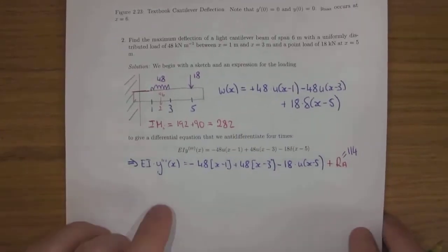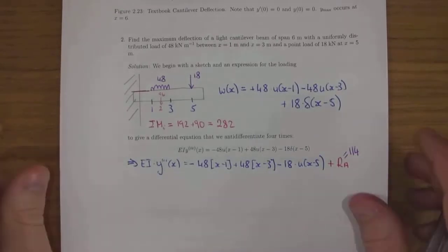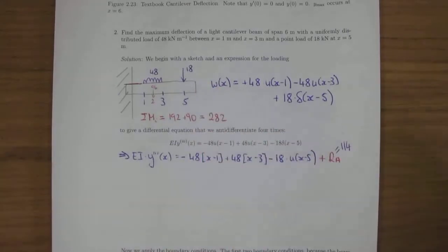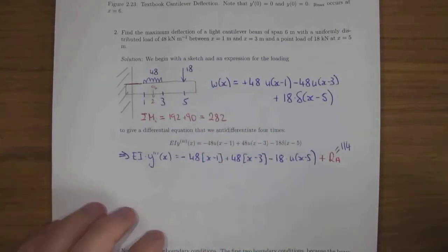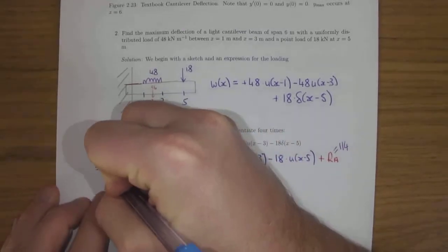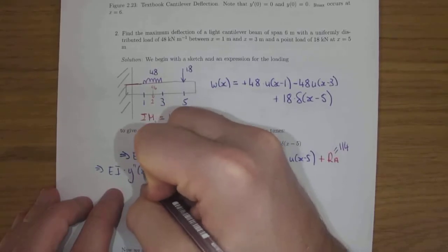Now the reason I actually don't do it like this in the notes is because with a linear load I don't think it works the same way. I'm just not sure. I think you have to do bending moment at the end of 0. Okay. Next thing, antidifferentiate again. EI times antiderivative third derivative is second derivative.